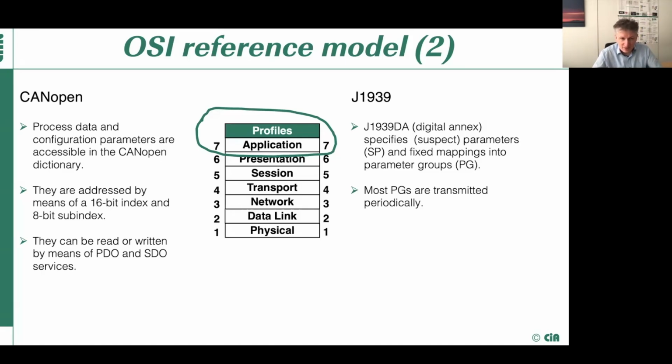This is one thing. The object dictionary in CANopen is constructed with index and subindex, and there could be very many of them. Just for information, for more details, you can look into our basic specification, and you can represent in general multiple applications in there with various parameters for configuration. This is not provided in J1939, but is also not needed there for the current usage.